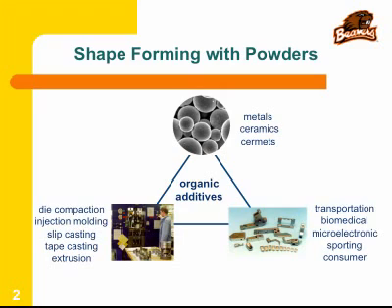In injection molding, you need the polymer to be a melt. So you heat it up, it goes from the solid state to the liquid state, and then you process that. Right? In the case of slip casting and tape casting, you dissolve the polymer in a solvent, right? And so the properties of what solvent dissolves which polymer, and so the interactions between the solvent and the polymer become important at that point.